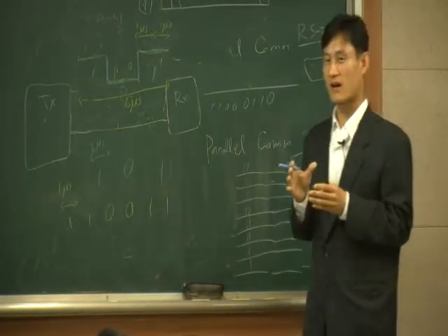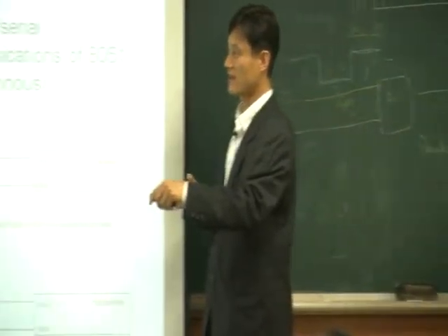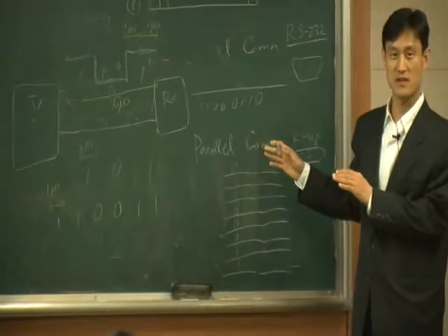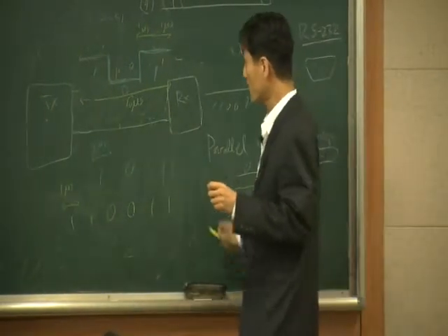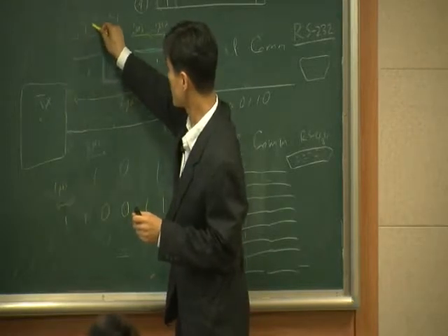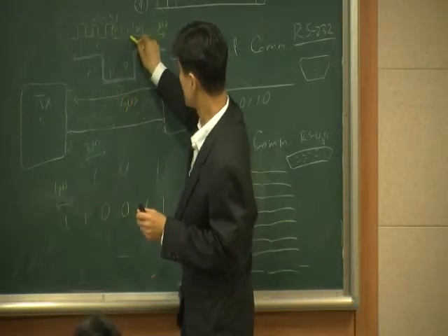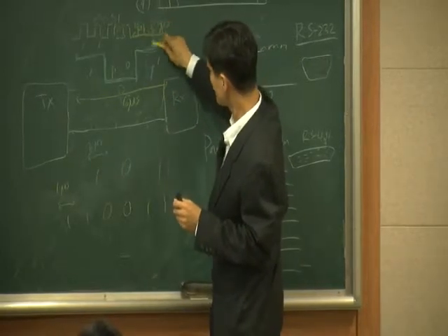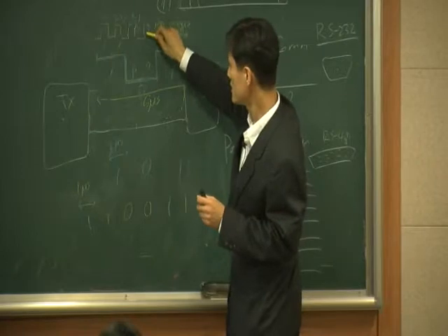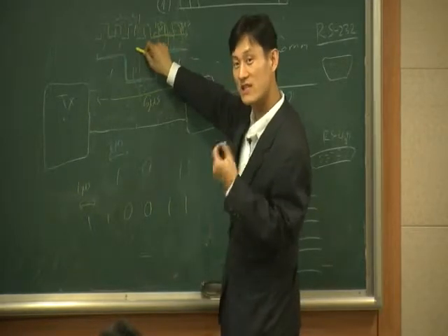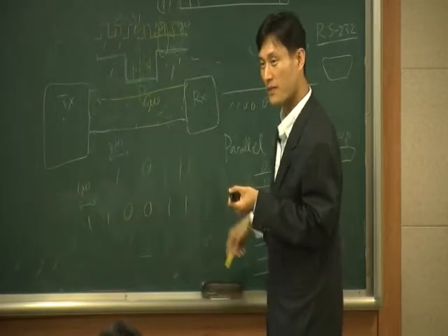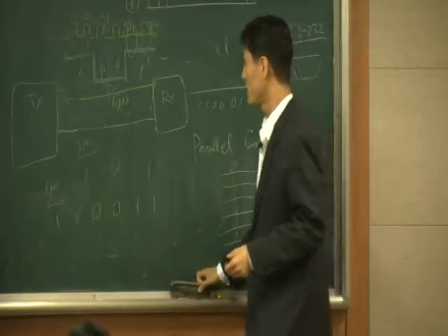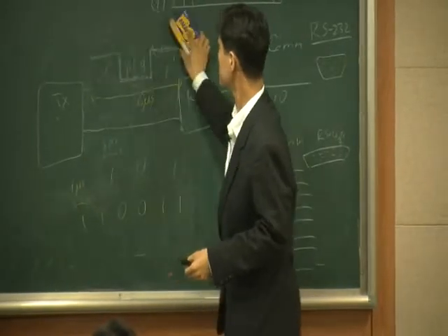If you have a clock, then there's no misunderstanding like this, right? Because if we have a clock, then we're going to have a clock edge every microsecond, like this. So based on this clock, we know that these are actually 2 samples. We can easily see it because there's a clock. But if there's no clock, like in this asynchronous case, then you can never see that.